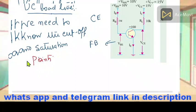The saturation region is that region where both the base emitter and collector emitter junctions are forward biased. The cutoff region is that region where both the base emitter and base collector junctions are reverse biased. In cutoff, the transistor is in the off state and is not conducting any current.